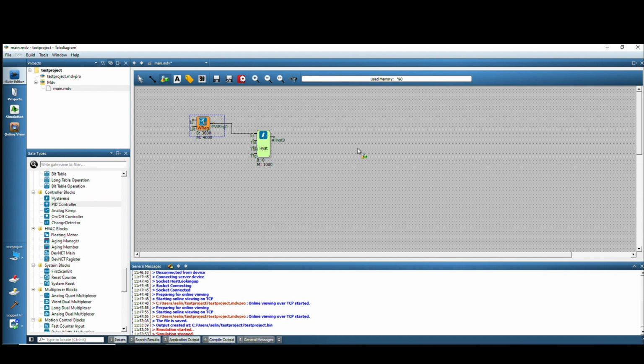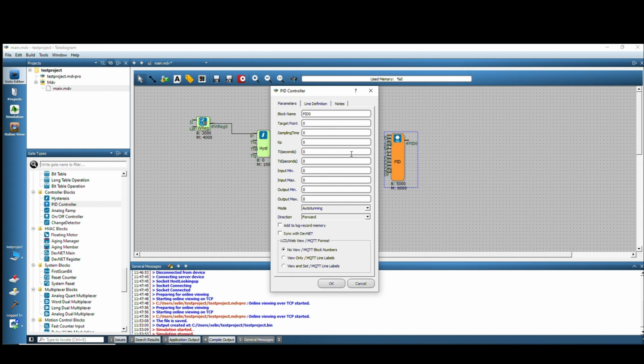Next, let's look at the FBD controller together. First, the data inside can also be entered from outside. There is a setpoint. For example, we can define the setpoint inside or enter it from outside. We have an area where we set the data sampling time. If we know the KP, T, TD values for the FBD, we can enter them here.